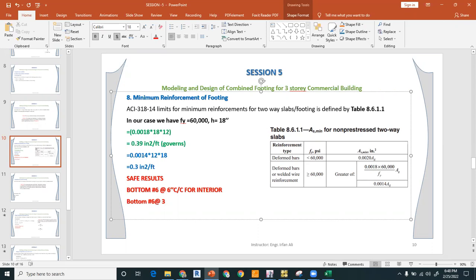Some of the students might say it is very much reinforcement, but this is not too much reinforcement, because we are limiting ourselves to a very small strip, which is 5 feet by 14 feet. So if you provide an overall strip, it will work with number 4 bar, right? So we have selected this just for demonstration and training purposes. We will use number 6 bar